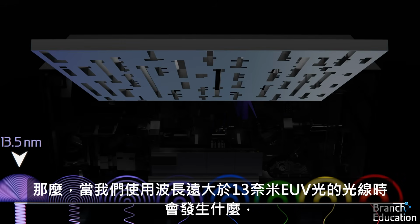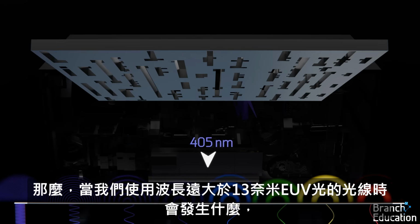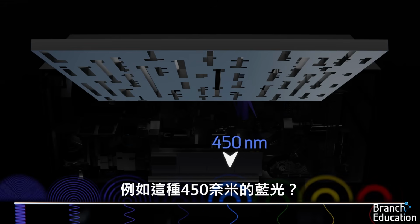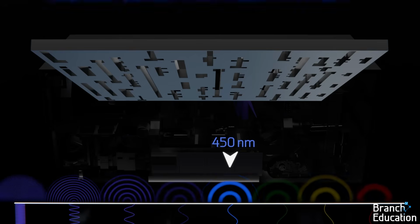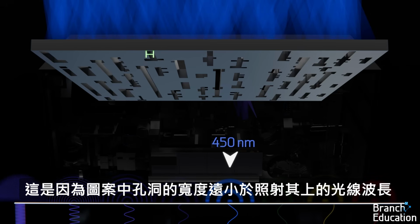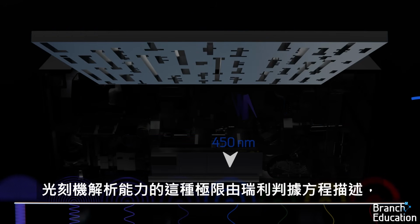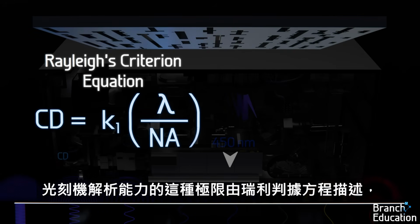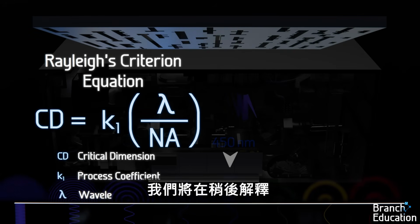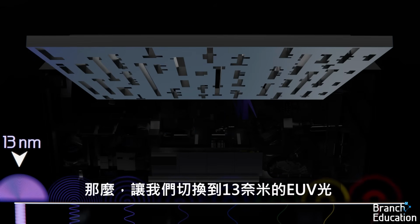So what happens when we use a wavelength of light that's substantially larger than the 13 nanometer EUV light, such as this 450 nanometer blue light? Well, when this large wavelength light hits, the pattern is almost entirely lost. This is due to the width of the holes in the pattern being substantially smaller than the wavelength of light hitting it. This limit to the resolving power of the lithography machine is described in Rayleigh's criterion equation, which we will explain later. So let's switch to 13 nanometer EUV light.